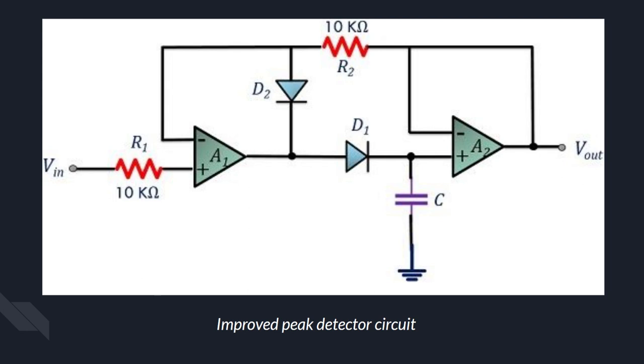What do we mean by the recovery time of an op-amp? It refers to the time it takes for an op-amp to recover its ability to amplify signals after its output voltage has been distorted by applying an input that exceeds its rated values. If the input signal exceeds the op-amp ratings for any amount of time, we need to ensure it recovers quickly in order to continue its working, which is why it's important to either keep the voltage within the rating or to improve the op-amp's recovery time when subjected to such voltage.